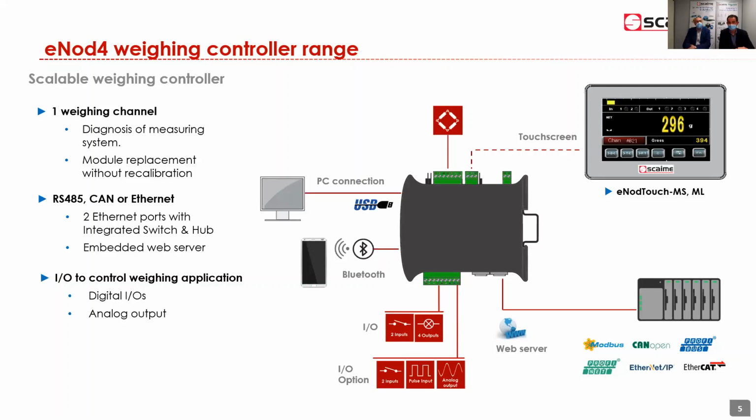About connectivity, these modules offer a large choice of connectivity to the main industrial fieldbus or industrial Ethernet networks. We have two hardware models. One hardware with RS485 with connectivity to Modbus RTU or Profibus, and this module also integrates CANopen connectivity with a CAN bus.